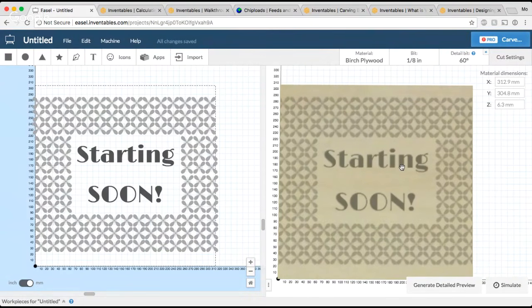I know we've talked about that a few times, but in the piggy bank article episode, where I talk about the new Easel features, 2-stage carves was one of those features. So that's a helpful guide if you're just learning how to use 2-stage carves, and it's a good way to save you a lot of time if you have a really detailed project.